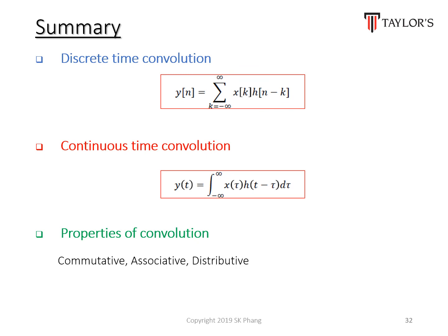And this is the summary of what you have learned today. First, you learn about discrete time convolutions, where you have three methods. One is a mathematical method where you apply directly the formula. Two is a graphical method where you reflect one of the signals and then you slide it to the right, and then you find out the superimposed multiplications and additions of them. And the third one is to draw a table, and then you just multiply both the elements together to find out what is the final answer. And I would personally prefer method number 3 for discrete time convolution.